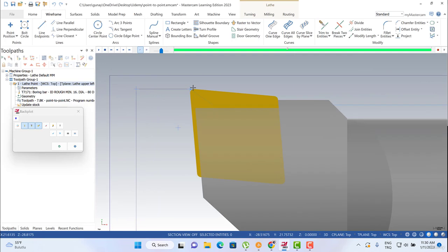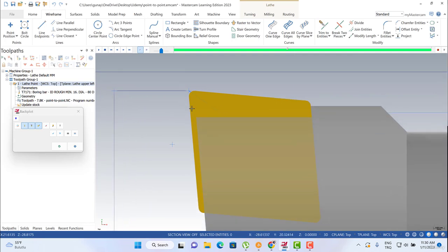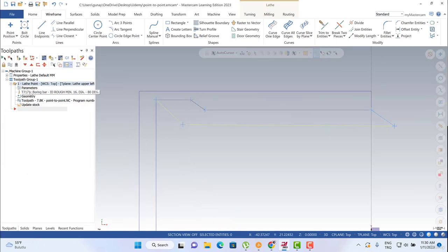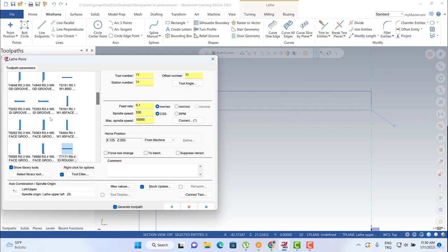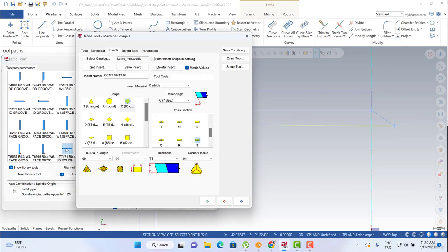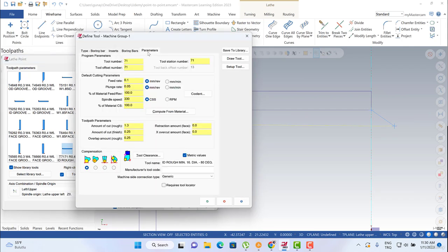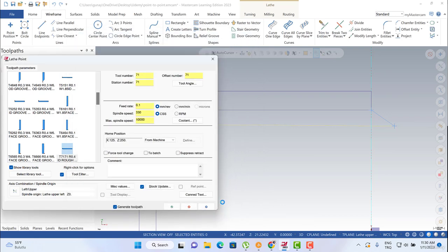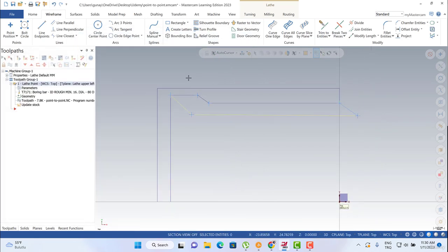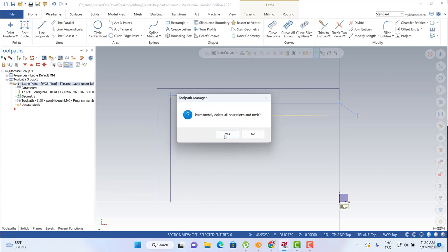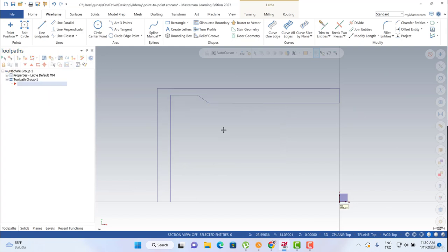Okay, we cannot calculate our tool radius compensation like this. When I turn to the parameters and double click on my tool, we're going to see the parameters and the compensation type. So according to my compensation type, I need to organize my points. So let's create it together.